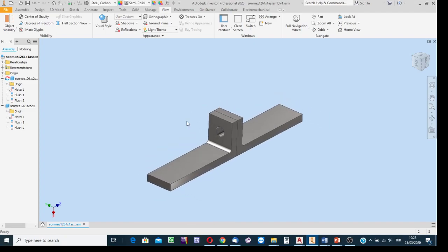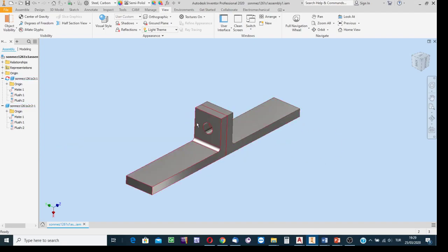Okay. Using bolt-nut type joints, using bolts and nuts to connect the components to each other, to be able to decrease the surface pressure between the head of the bolt or head of the cap screw and the surface of the component, and also to be able to prevent possible damages, scribings over the surface of the workpiece, we use intermediate machine elements between the surface of the component and the head of the bolt, or between the surface of the nut and the surface of the component.